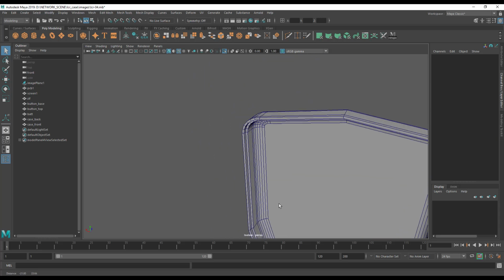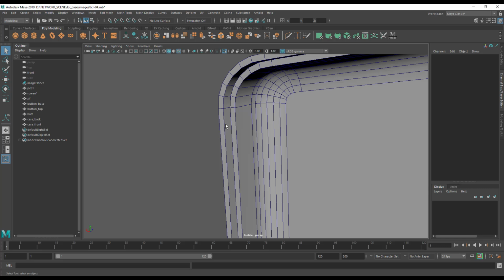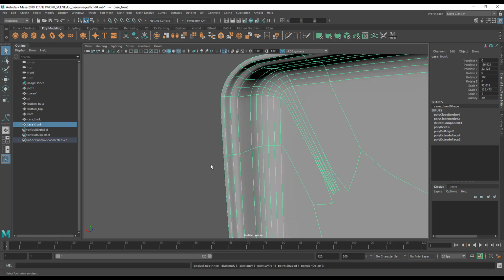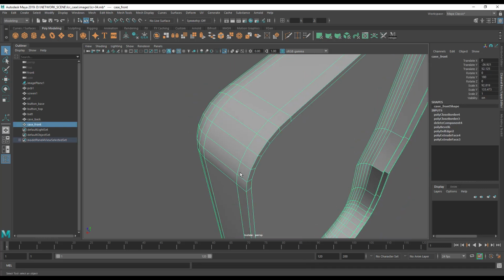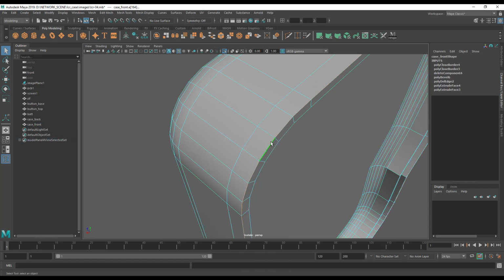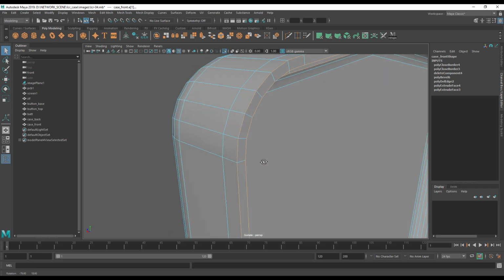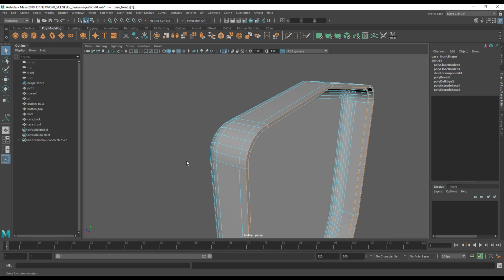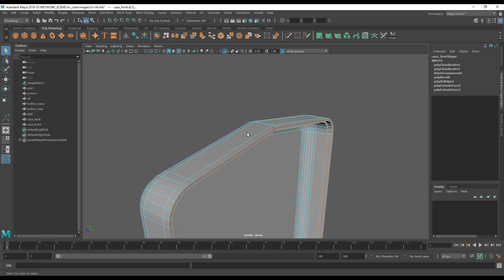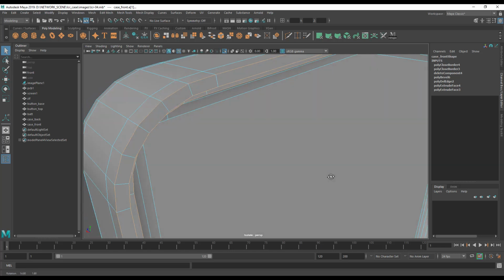Now the other issue we're going to have once again is the edges here. If I smooth, you'll see this becomes like a dog's breakfast, no good to anyone. So edge, again, very simple procedure. And what we're looking for here is accuracy. So using the bevel tool to put the supporting edges in will allow us to make the supporting edge the exact same distance as we made the previous ones, which was 0.1 on the bevel.